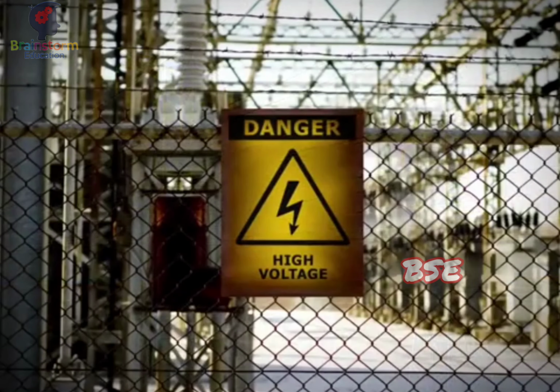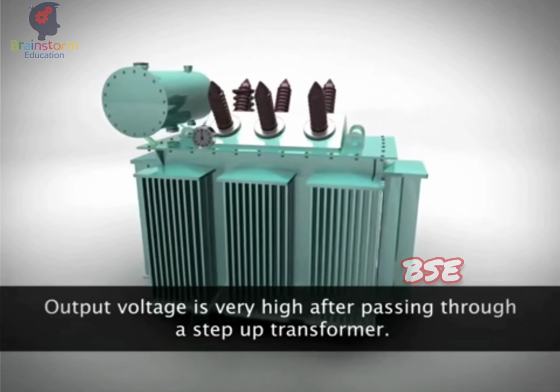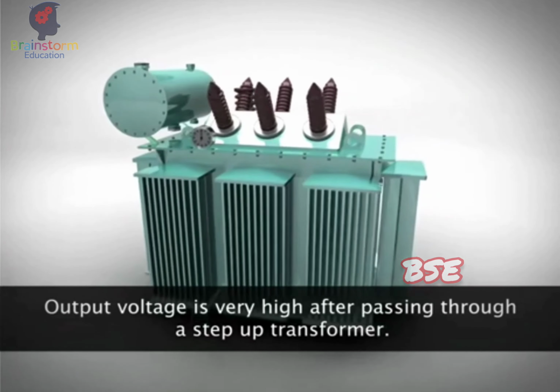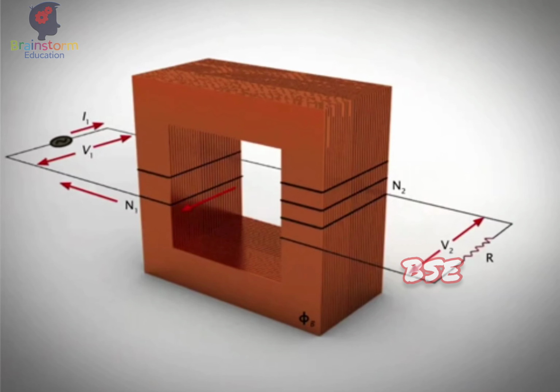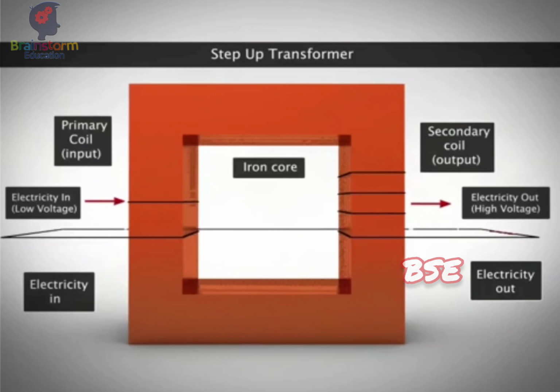Therefore, electricity immediately after generation is stepped up to a very high voltage using a step-up transformer. Since the number of turns in the secondary coil in the step-up transformer is more than that of the primary coil, the output voltage is very high.